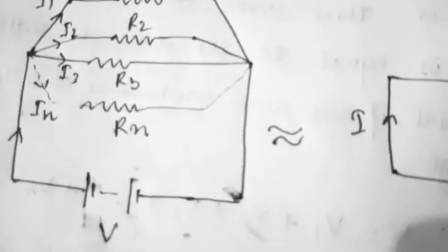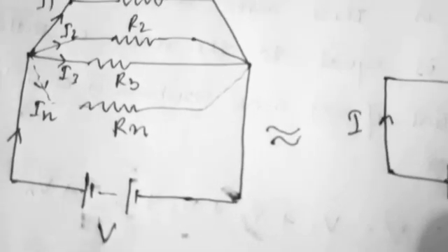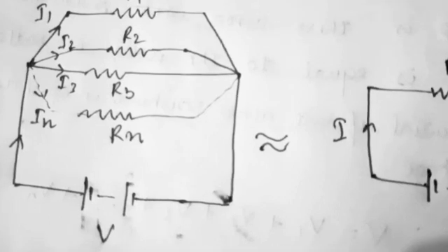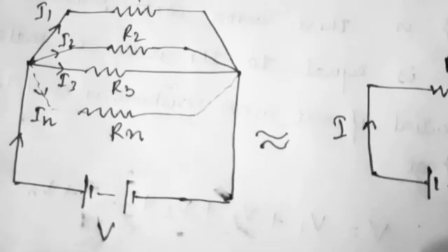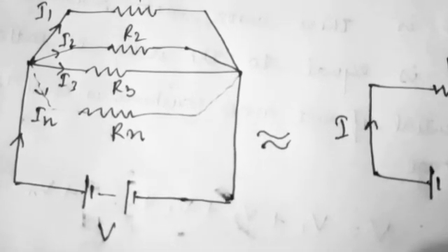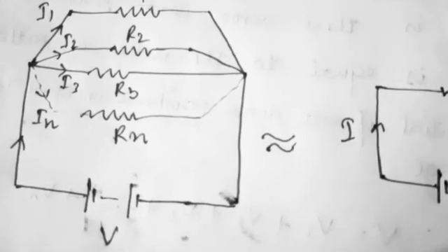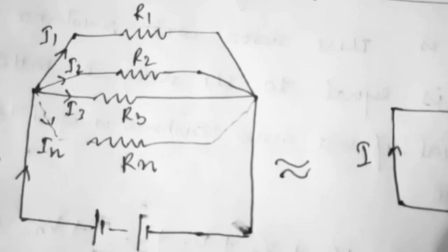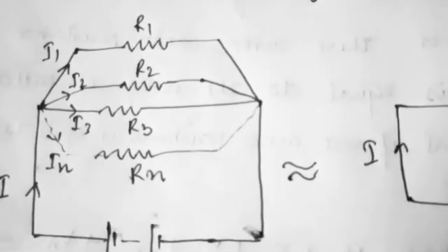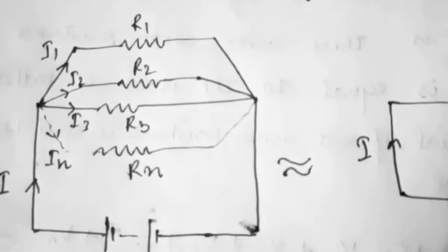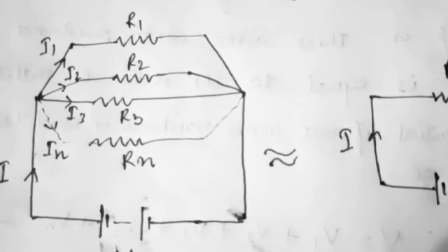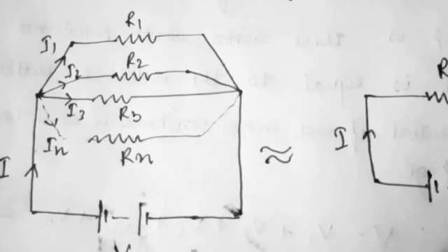In the next lecture, we'll study numericals. And for numericals, I'll give you a brief hint. Whenever you see a circuit, try to draw the source current. Wherever the source current is the same, those elements are in series combination, and wherever the source current distributes or divides along various paths, those paths where it is being distributed are in parallel. Once I solve the numerical, I'll tell you that in detail.